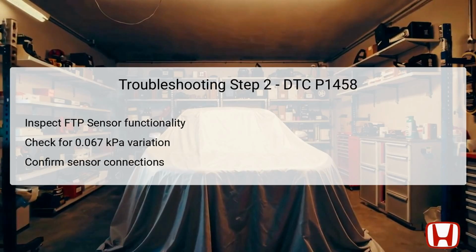It is crucial to verify that the sensor connections are secure and undamaged, as compromised connections may also lead to erratic sensor behavior. This step focuses on ascertaining the operational capability of the FTP sensor and serves as a foundational aspect of diagnosing the P1458 code effectively.